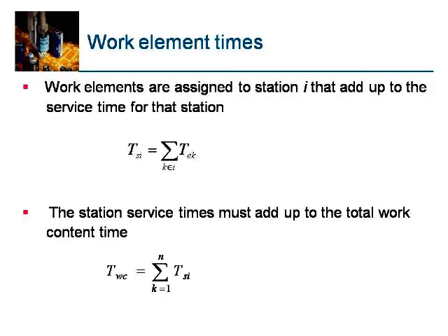Suppose the total WC is equal to 4 minutes, and you have 4 workstations, and each workstation can spend a maximum of 1 minute. If the work elements are assigned and each takes only 1 minute, it is a perfectly balanced line. If it is not 1 minute, say one is 70 seconds and the other is taking 90 seconds, then it is called an unbalanced line, and it leads to starving and blocking phenomena, which are not desired in a typical assembly line.